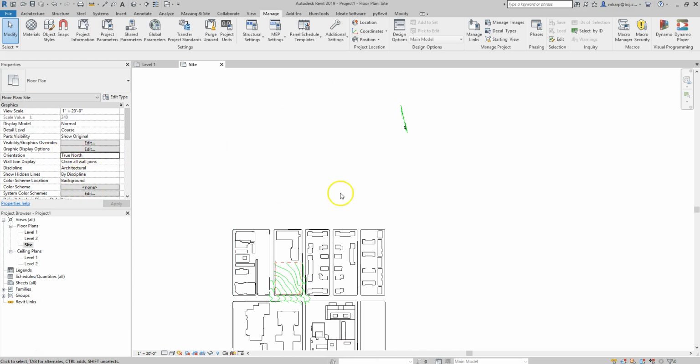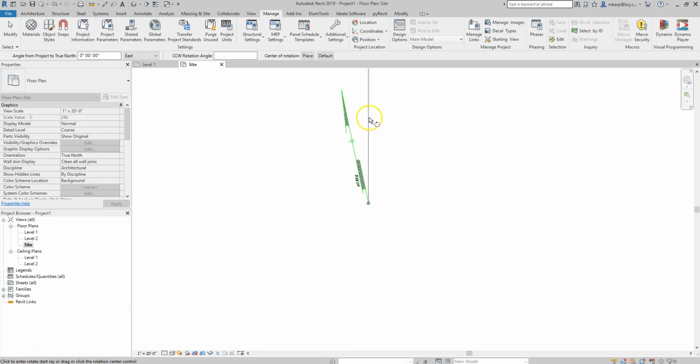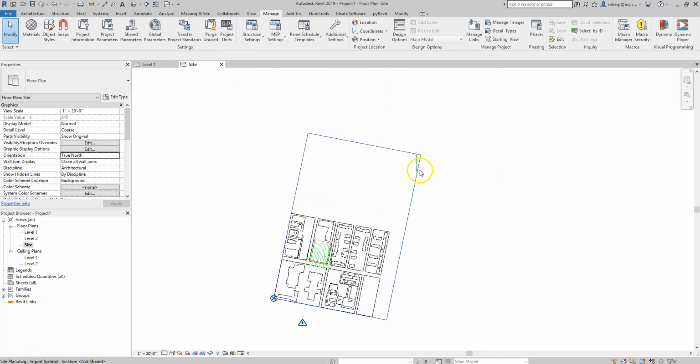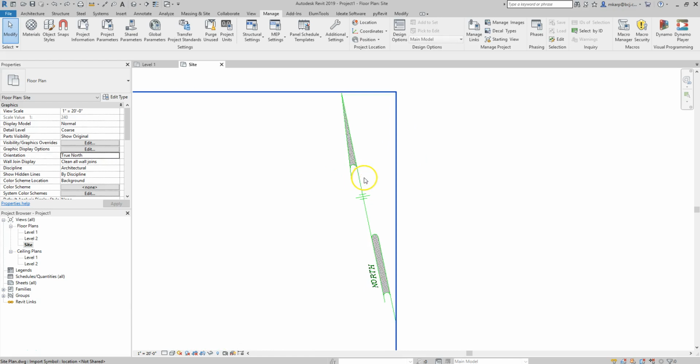So now that we're on True North, we can actually edit our position. So here it says Rotate True North. So what I'm going to do is drag my little rotation piece over here. I'm going to make sure I move it onto the same line. All right. And so what that did was it changed my true north to be perfectly straight up and down. So I'm going to hit undo and just do that again to go through it.